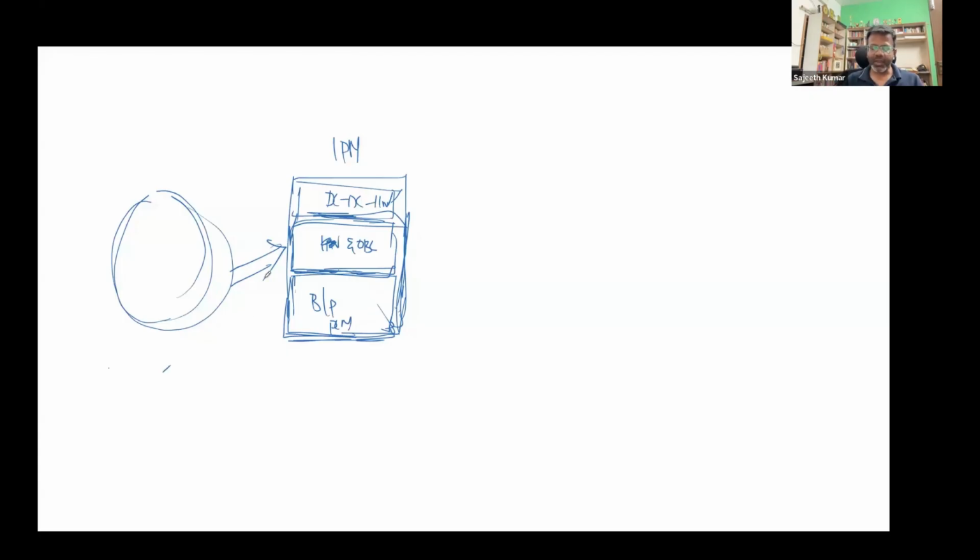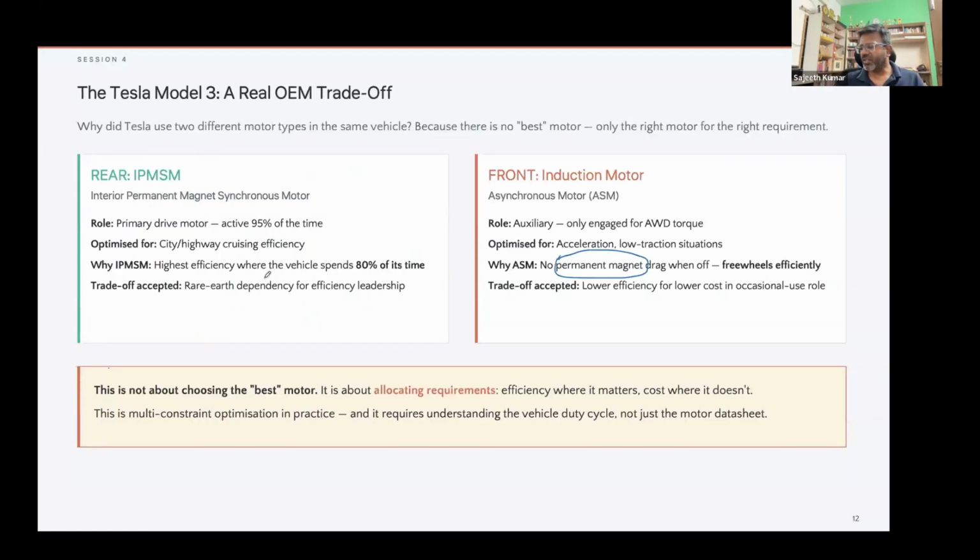I mean, aerodynamic cooling is also possible. But that is not just sufficient, right? You need to look at various other aspects of it as well. So, this is in response to the question Mr. Rojo Kurian had put up there. Most importantly, what we do in this case is we limit our charge and discharge to 0.5 C, right? Which means the thermal gradient because of the internal resistance, we are trying to restrict to a great extent as well. So that is basically how we are controlling it.